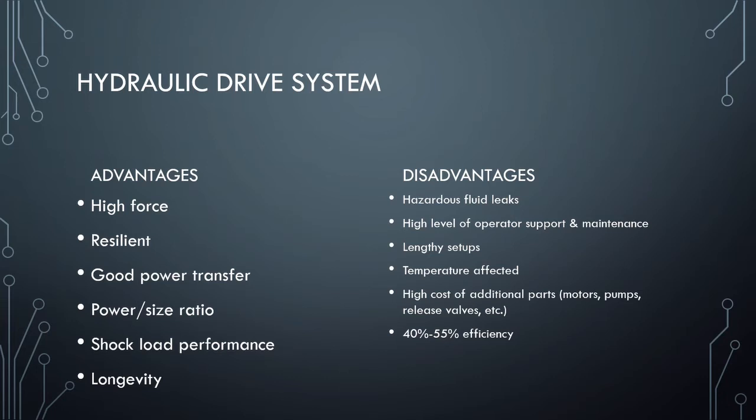But it's really hard to get a high efficiency out of these units. They also can have a really good power to size ratio. So I talked about how the pneumatic drive systems have to be appropriately sized. There has to be enough space. The power to size ratio on hydraulic drive systems is a little bit better than that. Because they're a stronger system, you don't need as large of a drive system to get the same amount of power if you're using a hydraulic system compared to a pneumatic.